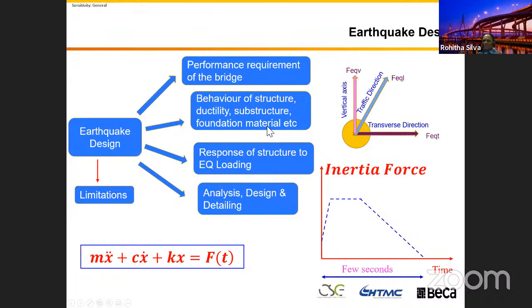Then see what sort of bridge you're going to build. See the ductility, what sort of foundation system you're going to put, and what sort of material you're going to put your pile in. Is it clay, or soil, or rock? If it's a strong rock or weathered rock, if it is soil, if it's stiff clay or subsoil, all this ground condition, you need to understand that.